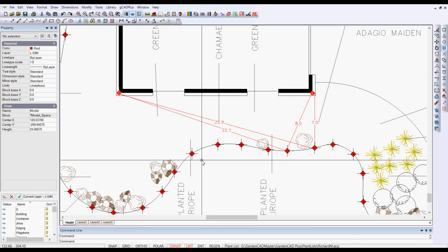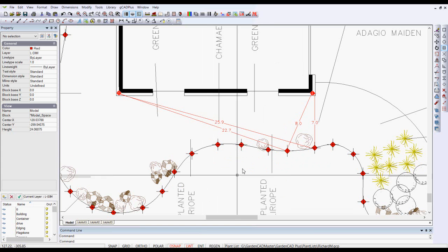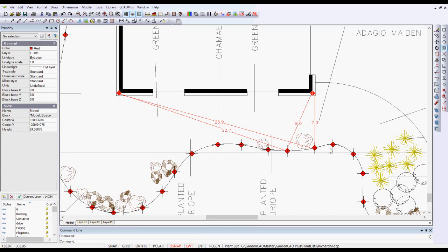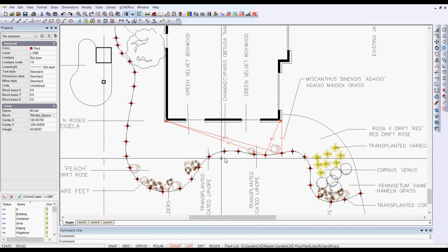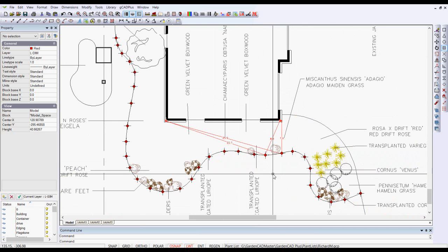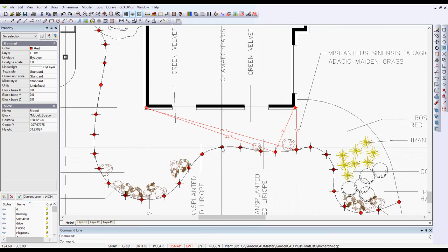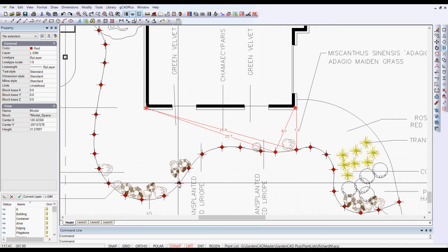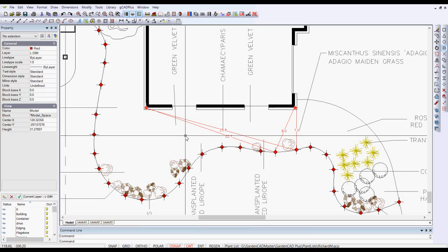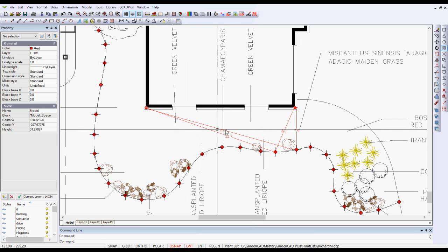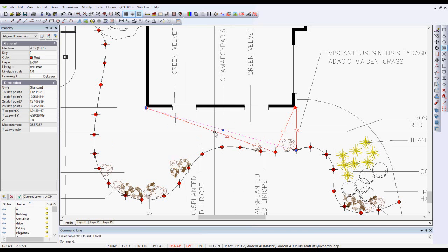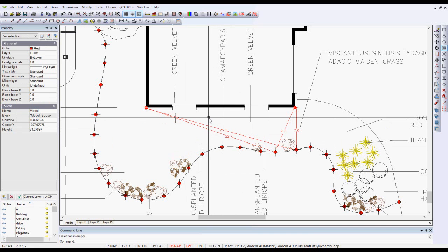They may not need this number of control points, and you might just put some dimensions for some critical ones, and they can work things out in the intermediate thing. So a control point there, maybe this one here, and another one down there will give you the answers of what you need. So I have all of those dimensions have been drawn on a layer LDIM, so it's a